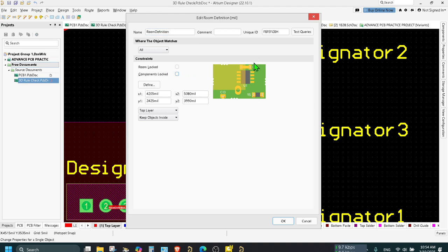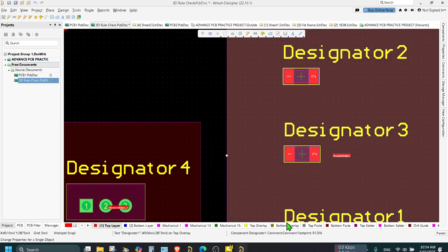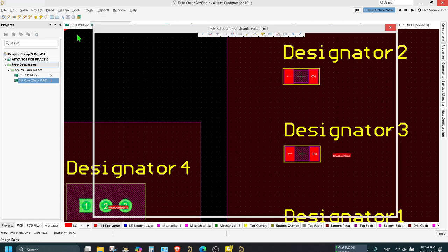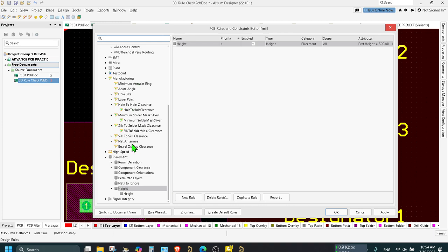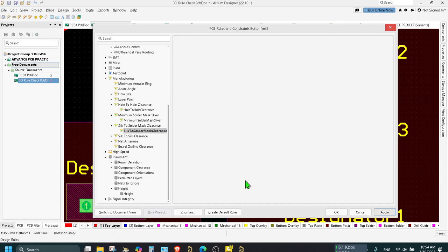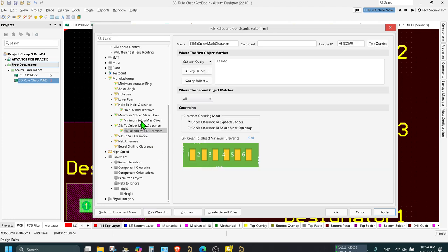And some other. There is this round which looks like scale to, at the bottom the manufacturing part, scale to solder mask clearance. We set it to 0, this 0, and this we set 0. Okay.